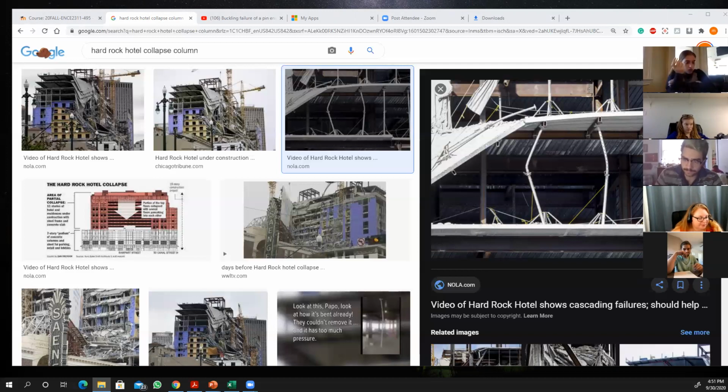Or in the other case, if you're designing a certain section in the hotel that's going to carry the AC units, that's going to be a huge point load applied to a certain section, so you have to add additional columns and additional strong, durable girders and beams to support that load. Does that make sense? You have to know where the load starts, and then how it's distributed, and how it goes from the top into the foundation.